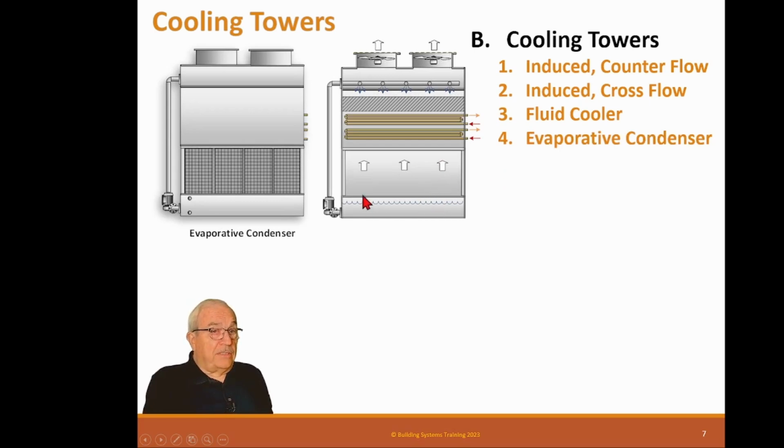An evaporative condenser is exactly the same thing as a fluid cooler, except here we have a refrigerant circuit. So we have hot refrigerant coming in, and these are used in places like supermarkets and places that have cold boxes and freezer boxes, and they have several circuits in one evaporative condenser. So they can run 3 or 4 different refrigerant circuits in these tubes. And everything else about this evaporative condenser is exactly like a fluid cooler, except instead of water to water, we've got refrigerant to water cooling. Same problem. You can't use a heat exchanger out here because it's refrigerant direct into there. But when these start scaling up, they're really expensive, so you have to be careful with that too.